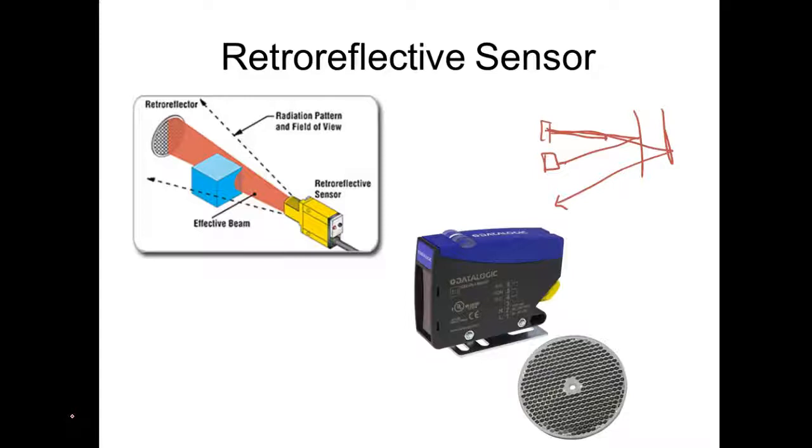It's only got one, even on fiber. Even if I used a common head to do either the retroreflective or through-beam with fiber, we'd still have to run two fiber cables out there, right? You understand? Here we wouldn't have to run any fiber at all, unless we'll see.